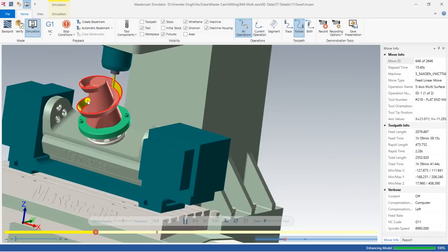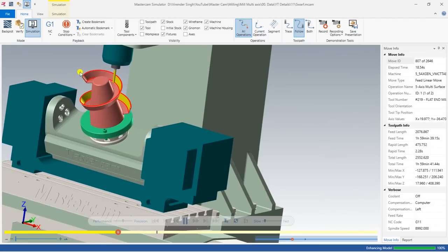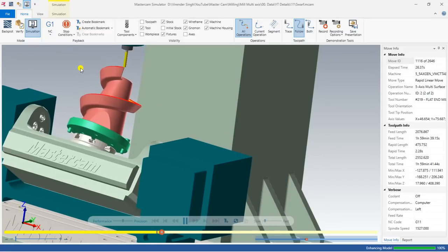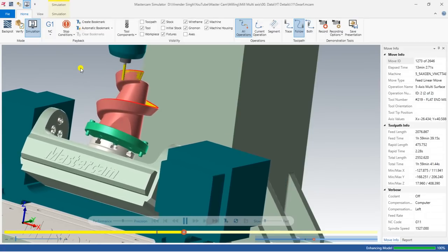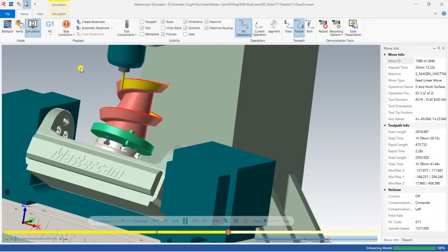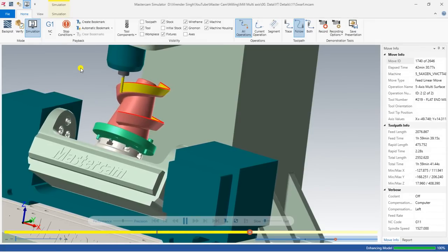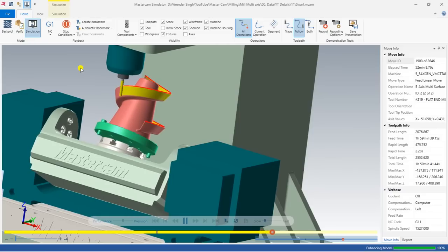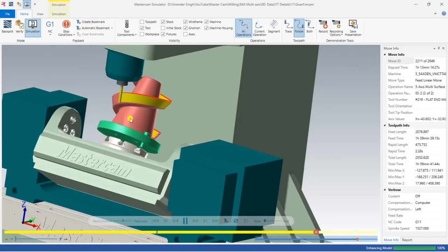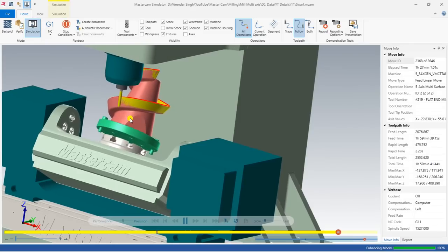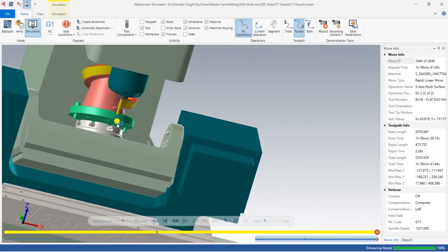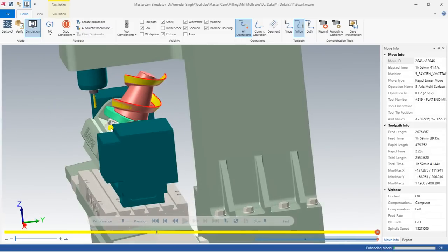Swarf toolpath is the kind of toolpath where we cut with the complete flute area of the tool. The tool automatically decides where it has to cut, and the tool automatically tilts according to the surface area, and cuts with the complete flute length. We will discuss the toolpath parameters and learn step by step the details of this strategy. Swarf toolpath is one of the toolpaths used most in Mastercam multi-axis.